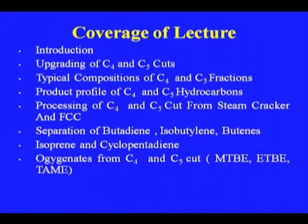This will be the coverage of the lecture: an introduction on why we are going for the recovery of the C4 and C5 gases, what is the importance of these C4 and C5 hydrocarbons, and the upgrading of the C4 and C5 cuts. How to separate them, because many of the hydrocarbon fractions you get here have close boiling points. This only became possible with the development of adsorption technology and some solvents. Earlier, the separation of close boiling components was difficult, and in C5 also the same problem was there.